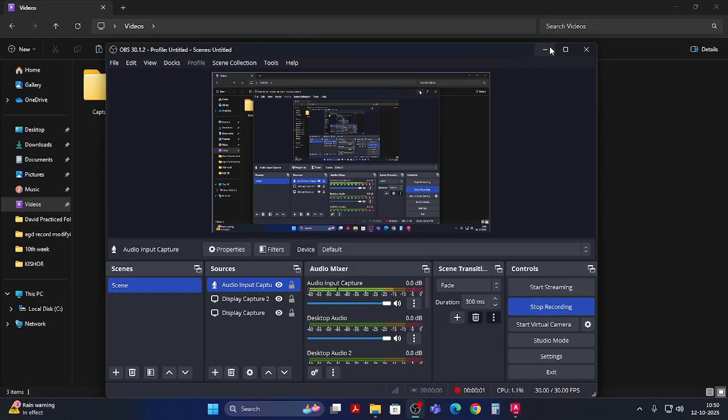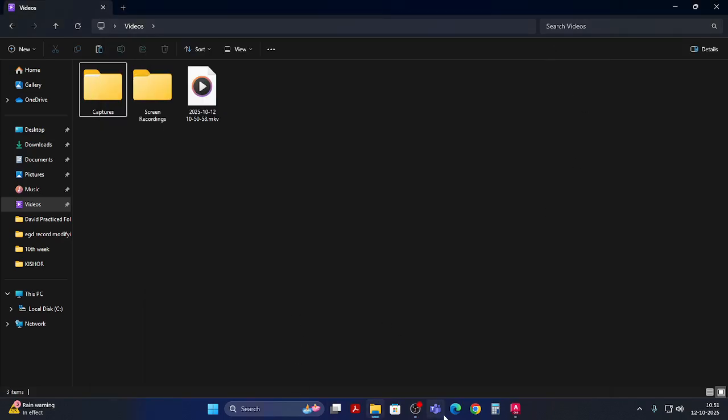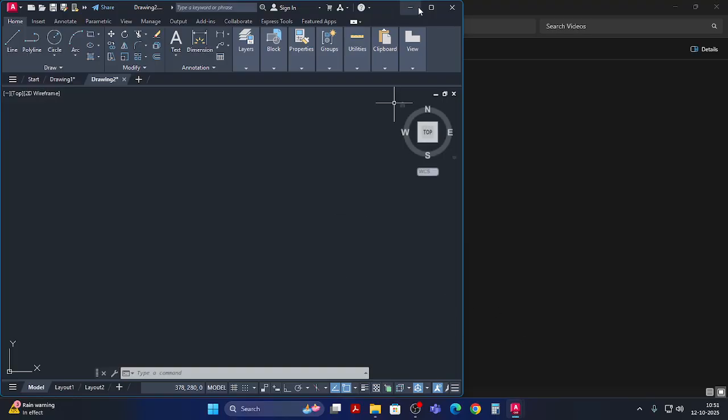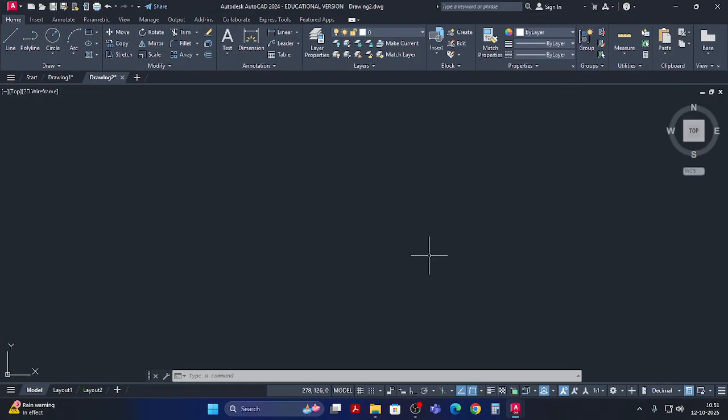Okay, let us see the 8th week, third question, development of surface. The question you refer in the manual. I'll tell that pentagonal prism, base side 90 and axis length 150, height of the prism 150. Let us draw that. I already set units and limits, so you keep it in 2D mode,